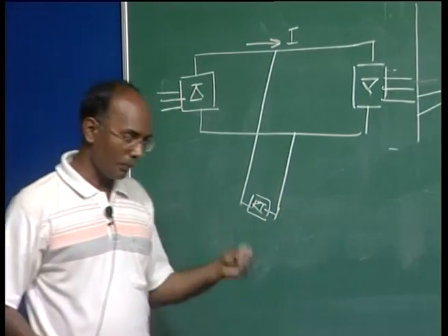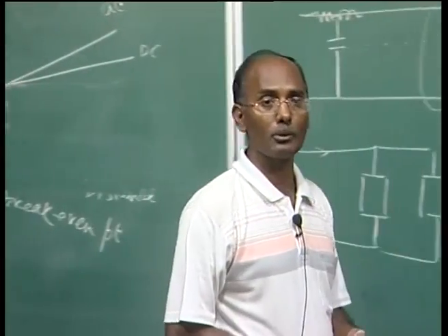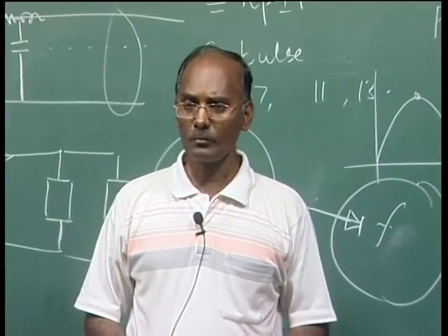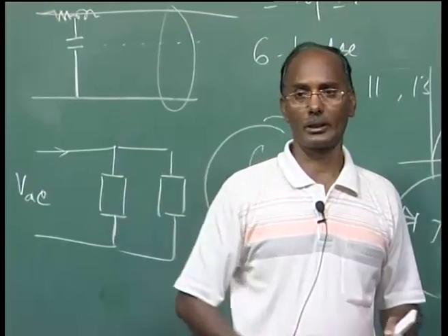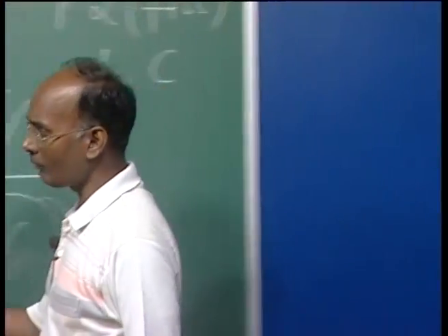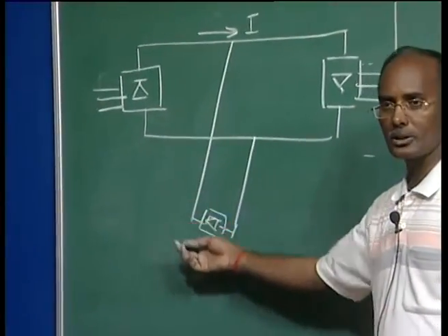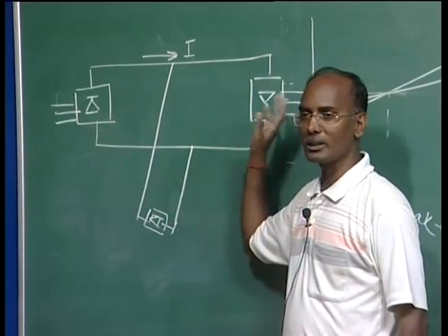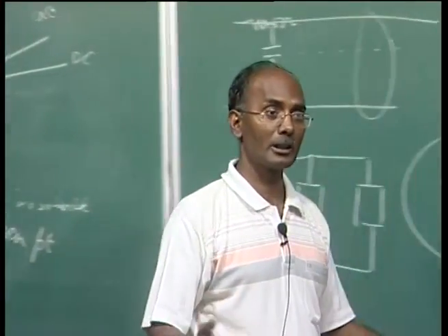So I mean to tell that point-to-point transmission is not so practically feasible in HVDC transmission system. Normally power must be injected from one end to another end, and that is a problem. Multi-terminal HVDC link is also possible, and it exists in the world, but only up to 3 terminals, not more than that. It is not desirable to go for multi-terminals, because the cost will also increase. Adding one terminal is not so simple. You have to go for all the substations, the converters, and the communication and controller equipment must be there. So the cost is increasing for tapping the power in between.